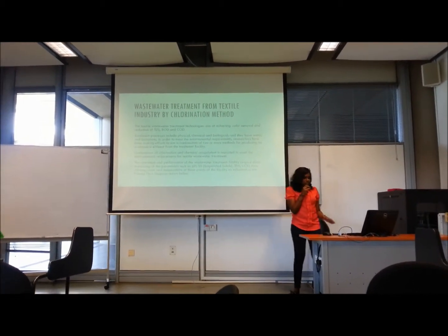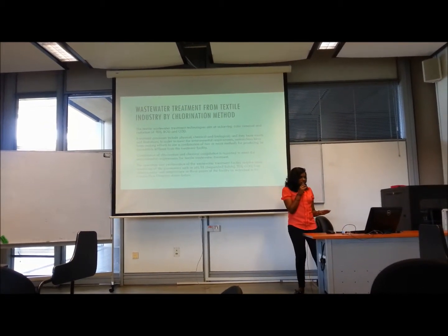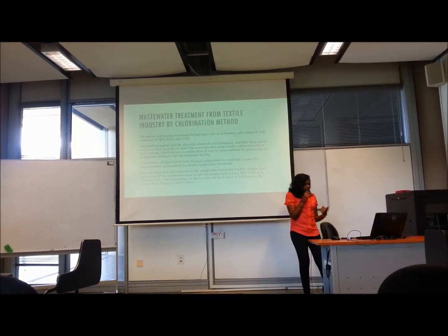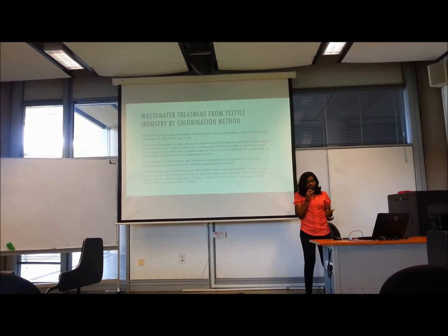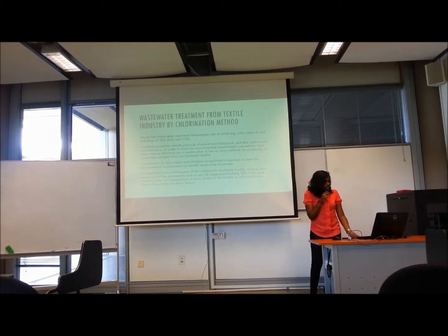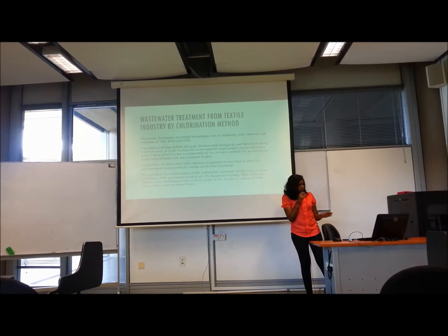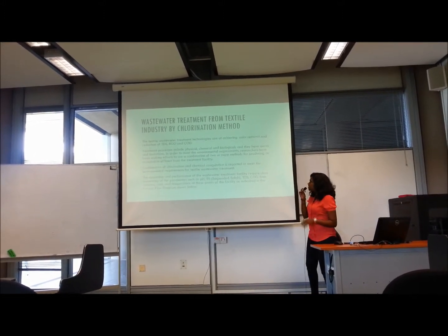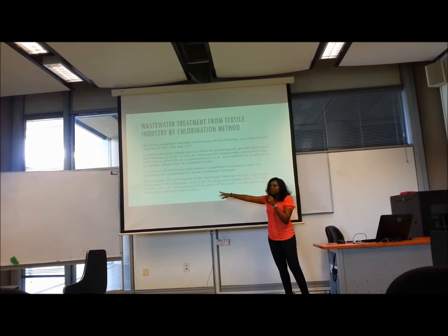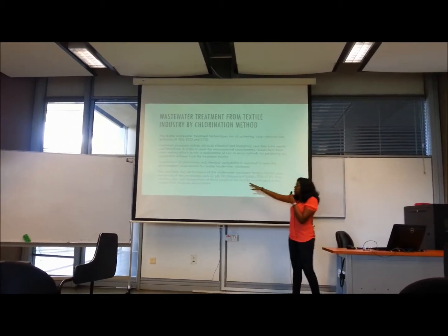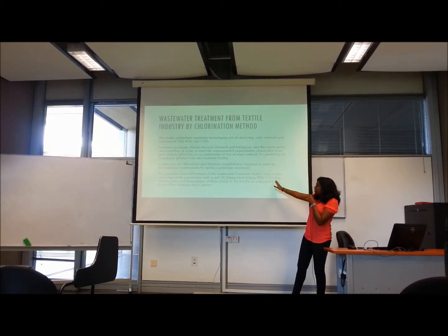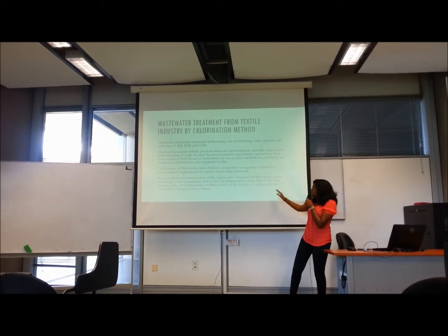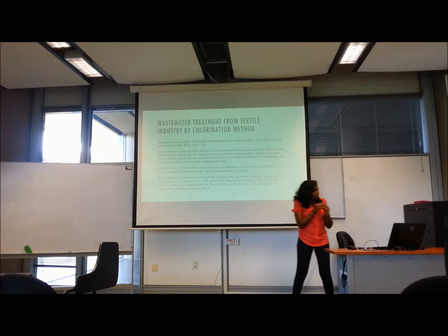What is TDS, BOD and COD? TDS is the total dissolved solids, while BOD is the biological oxygen demand and COD is the chemical oxygen demand. So the operation and performance of the wastewater treatment facility require close monitoring of the parameters that I mentioned, which are pH, of course you know the pH value, suspended solids, TDS, COD and free chlorine, color, and temperature at this point of the facility as indicated in the process flow diagram.